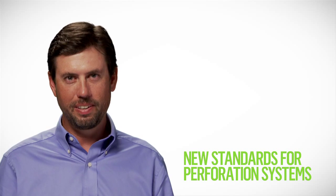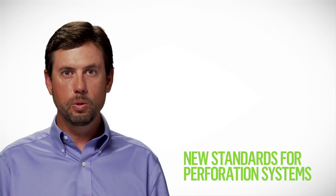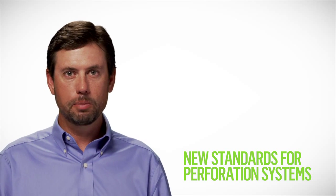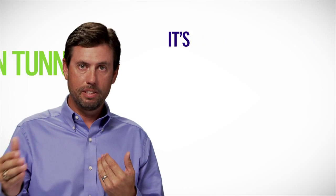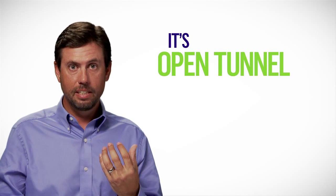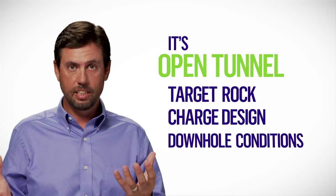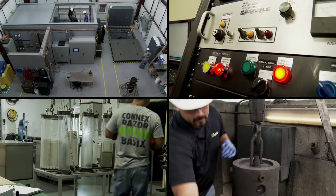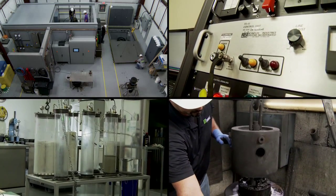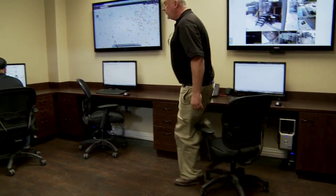As we move away from evaluating perforation performance in cement, we have to develop tools to predict how these products are going to perform downhole. The primary factor that plays into how well a perforation tunnel performs is the amount of open tunnel. Now, this is affected by the rock that you're perforating, the system and the charge design, and also the conditions that you're perforating in. The Geodynamics Perforation Flow Lab compares flow performance delivered by competing systems using natural rock targets under representative downhole conditions, systems, techniques, and scenarios.